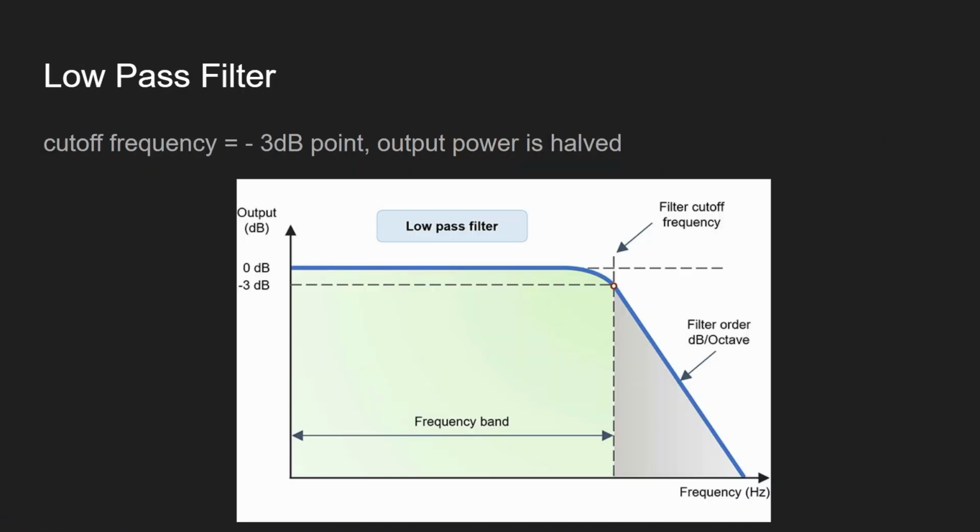Now, you see that I have talked about what 3 dB is, right? The minus 3 dB point is where the voltage is 1/√2, or the power is halved. This we call the 3 dB point. The output is halved. I've shown you the calculation.